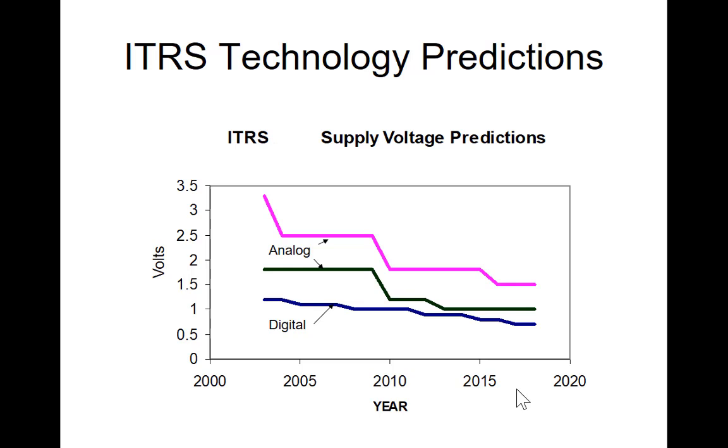Now, back at this point in time, there was typically a single supply voltage for larger digital ICs. Now a digital IC might have several supplies. It might have a 1.1, a 1, a 0.9, a 0.8 volt supply, and so forth. We're going to see that the power dissipation is strongly a function of supply voltage. So if you're in situations where you're not speed critical, you will oftentimes be able to drop the supply voltage down a little bit and save a lot of power dissipation.